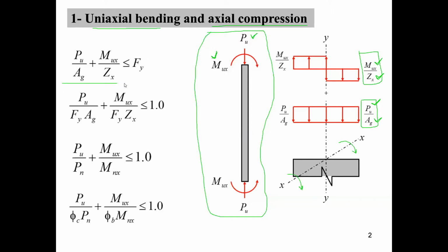The governing interaction equation will be Pu over Ag plus Mux over Zx is less than or equal to Fy.